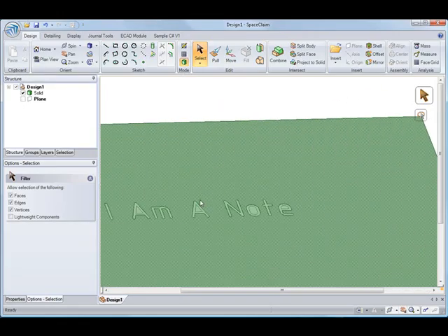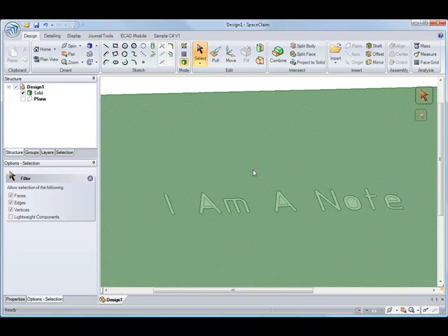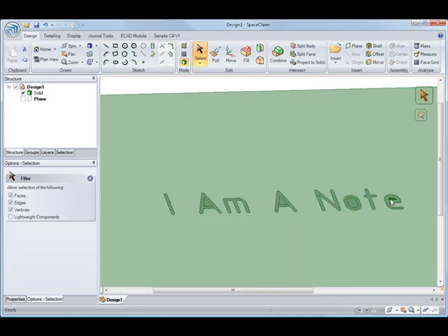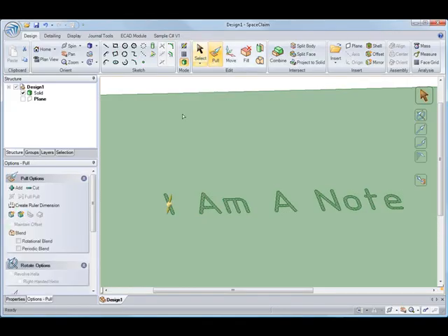So now if I want to create it in 3D, I just have to pull up all the surfaces. I'm going to do that with a nice big box select, and then I have to get rid of these little interior things. To help me, I'm going to turn off the edges in select, so those don't interfere with my selection, and I can quickly pick the interior things of the A, the O, and the E.